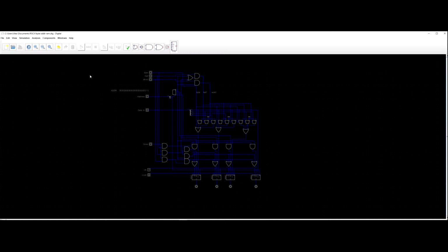And at work I'm using the 1508, which is 100 pins. About 84 of those pins are I/O. The rest are power, ground, clock pins, and the programming pins for it. So I basically have 84 input outputs that I can control, that are programmable, and I'm running them at 10 megahertz. I'm using two because if I use just one for all of it, I would overflow and fill up all the logic inside of a single one.